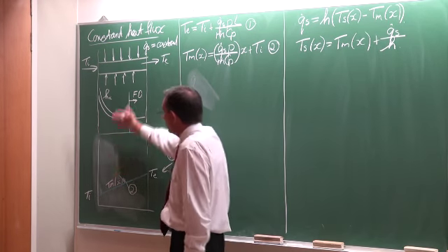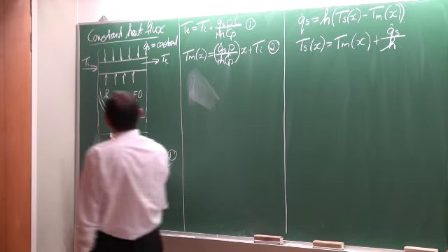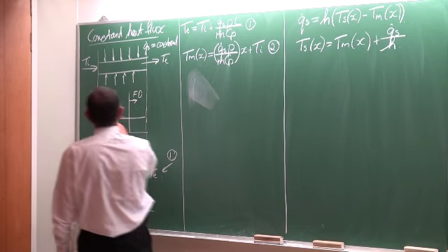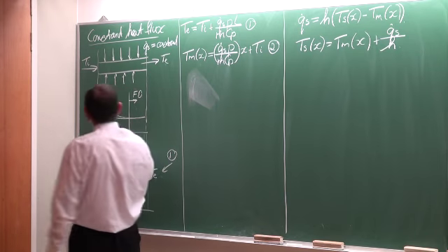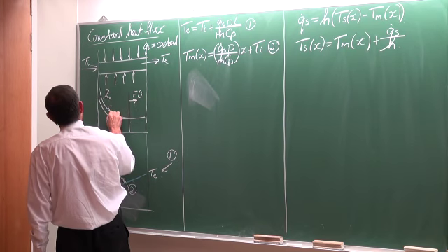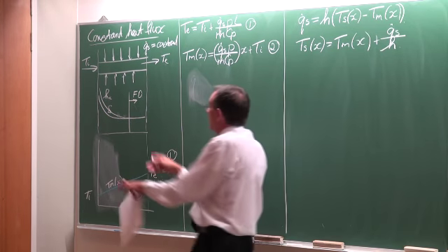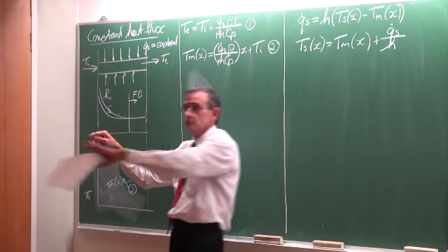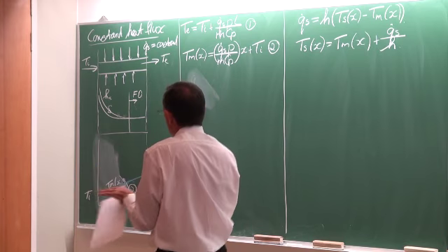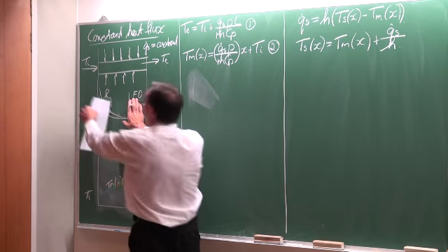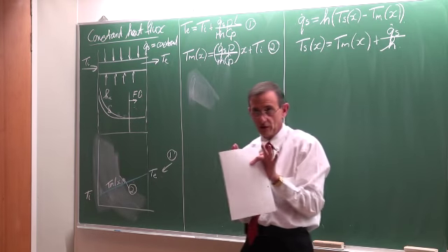In terms of what we've learned so far in this chapter and the previous chapter, the heat transfer coefficient would have a certain length before it is fully developed, and also the boundary layer thickness or the Cf value, whichever you want to use. And these lengths are not the same, except if the Prandtl number is 1, then they are the same. Okay. But in general, we have a region of developing flow and a region of fully developed flow.